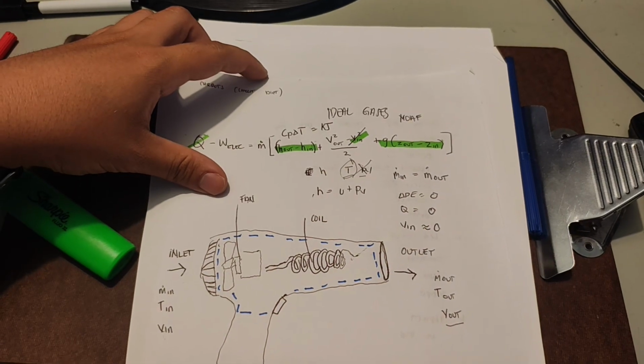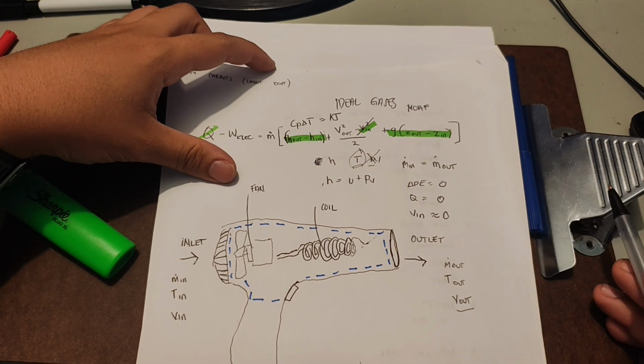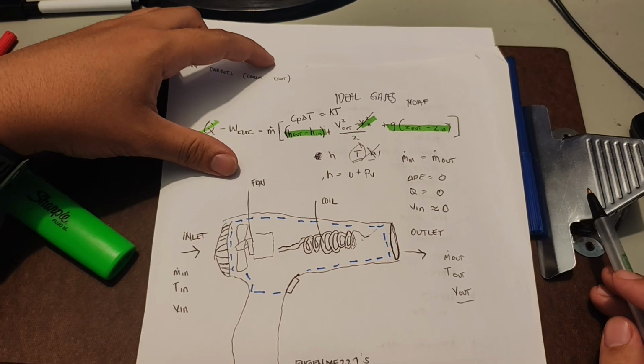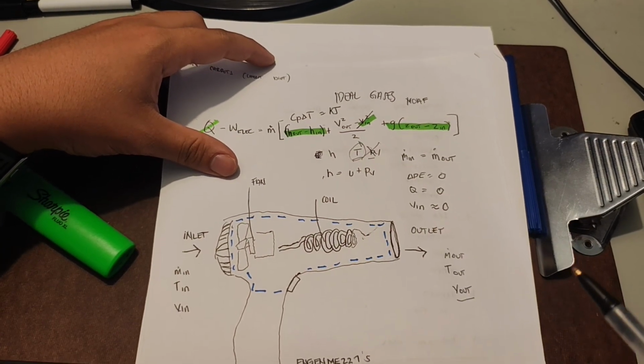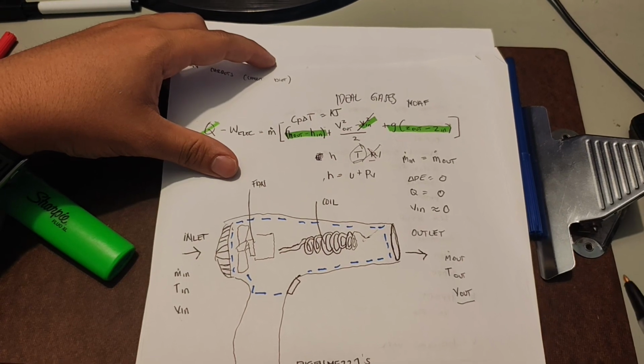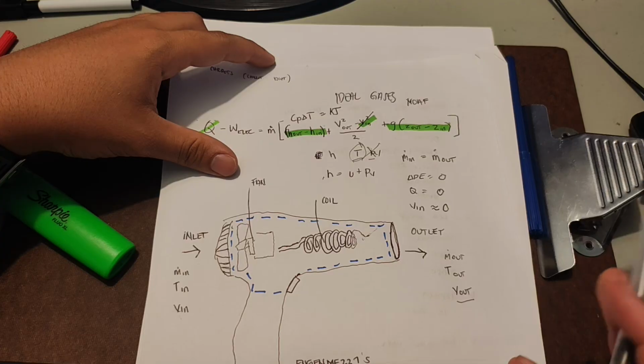Okay, so to add them together, you must divide the velocity term by 2000. So that 2000 accounts for the 1/2 in the formula, and the 1000 needed to convert to kilojoules. If you forget this, your answer will be off by a factor of 2,000.